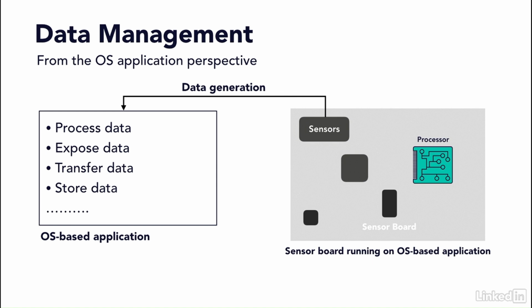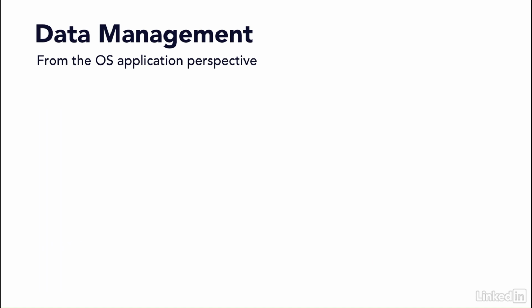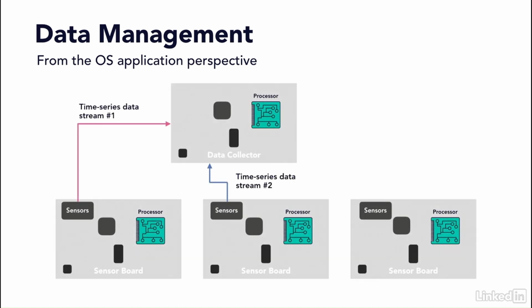network. Since the data usually needs to be stored locally in a file or a database structure in the device, our application needs to use a file system or database driver for such purpose. For some time series data that needs to be acquired from multiple sensors, we also need to have a mechanism of ensuring the accuracy of the data. For example, some inaccurate timestamps associated with a set of data may make a fresh set of data be considered as a stale one. Thus, data with inaccurate timestamps should be adjusted or filtered out, or else it may introduce errors for later analysis.